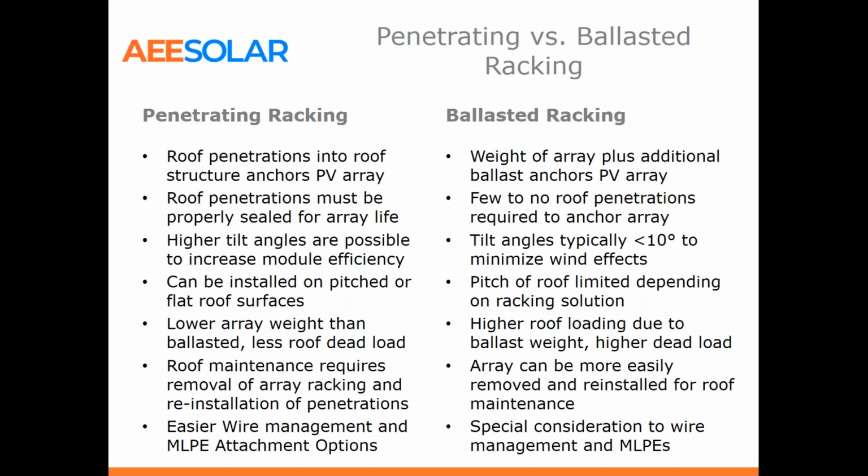We do also want to be careful about not damaging the roof if we have too much dead load added. However, we mentioned we also can easily maintain the roof if needed, remove the array and reinstall it. And also you have to worry about special wire management techniques and how to attach optimizers or microinverters or rapid shutdown devices to the module frames themselves rather than to the racking.